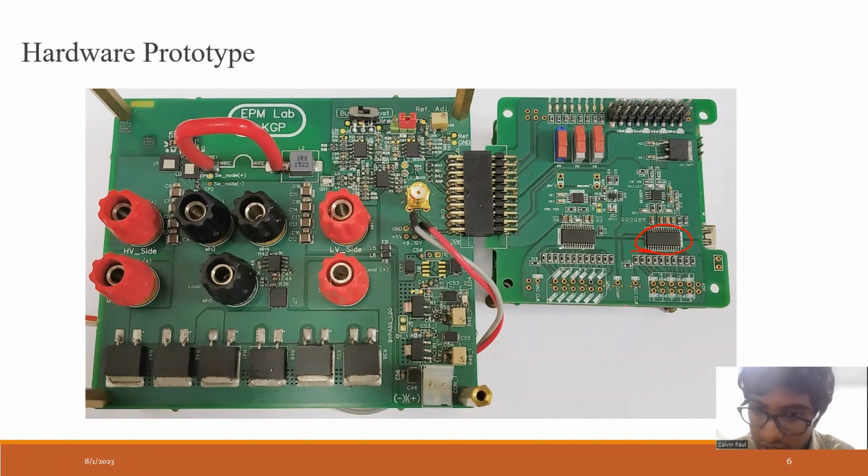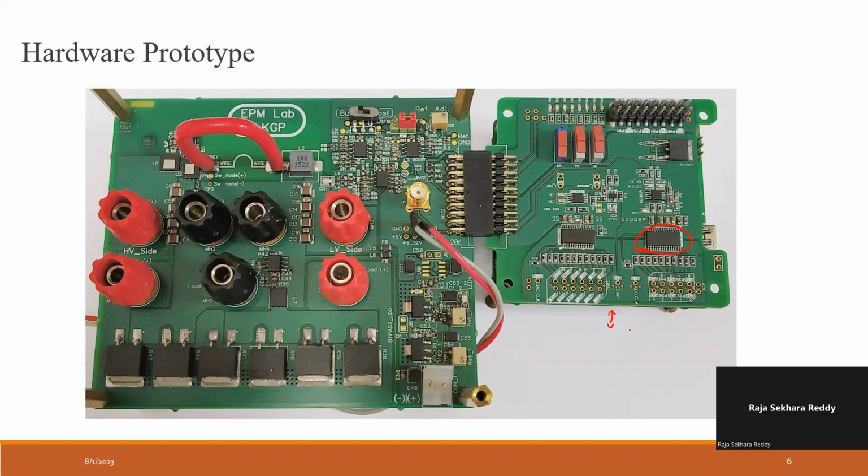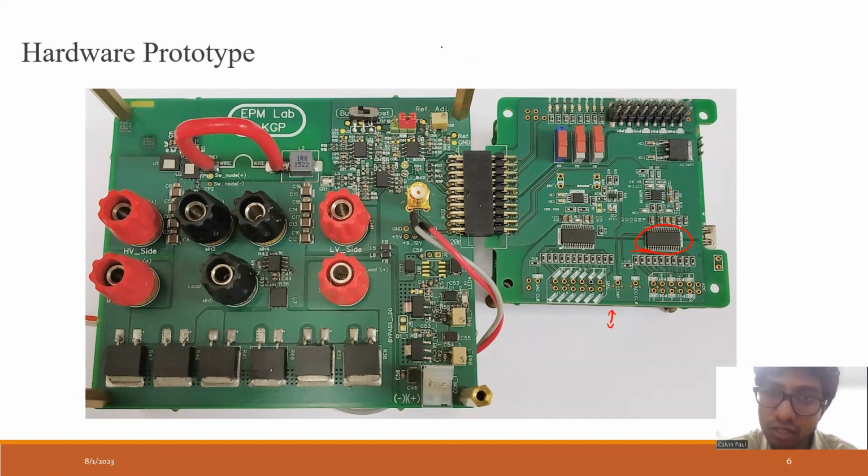This is the signal conditioning, and the FPGA is below this. That data will go to the FPGA, and it is digital data. Let us assume this is 1 volt. 1 volt is the input to my ADC. The ADC will generate a digital output. The ADC output could be serial, going 1 0 1 1 1 0 0 0, and it will go into the FPGA.